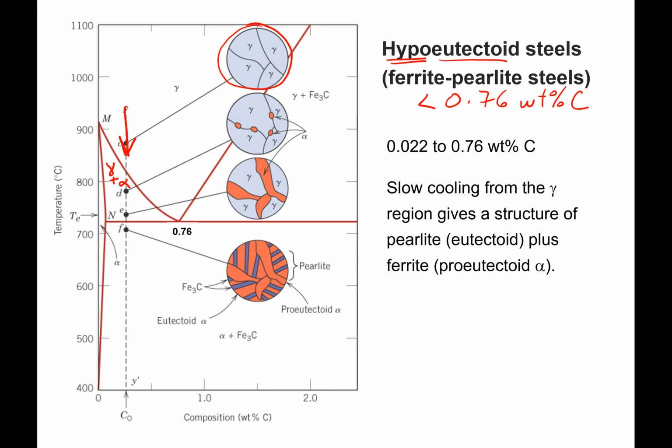So in the eutectic system, since you're forming a solid out of the liquid, you tended to get spherical particles. Now, since we're in a solid, we're looking for the fastest diffusion paths in our material, and those happen to be along grain boundaries. So there are two advantages of grain boundaries: you can get very rapid diffusion, and the other is that since grain boundaries have higher energy, by replacing them with a different phase, we can take advantage of eliminating the grain boundary energy. We'll get a phase boundary now instead.